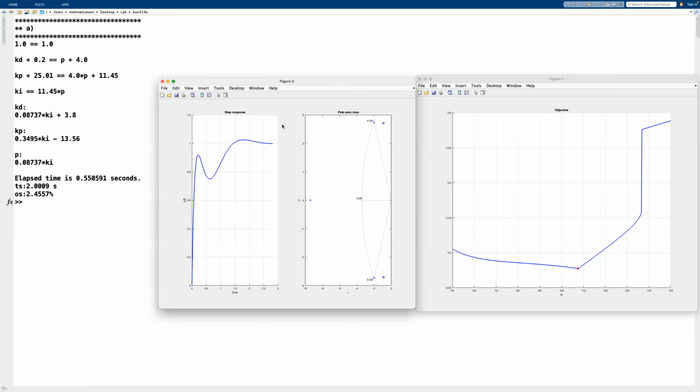For systems that have complex maneuvers, like an F16 or some plane dynamics, you wouldn't use dominant pole placement. Then you might want to end up in these acrobatic performances, and then you need that nonlinear dynamic, nonlinear behavior. That would make sense. But for other practical applications that we address in this course for now, they should behave like first order or second order systems.